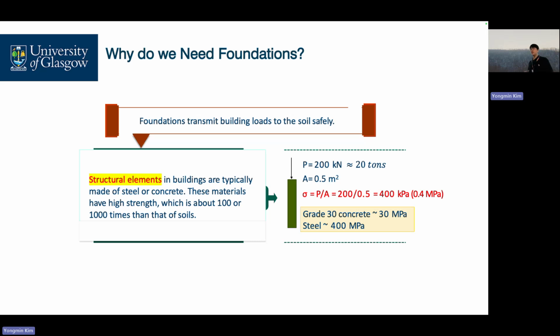Just to remind you of your civil engineering modules, concrete. What is your typical concrete grade? 30 and 40 megapascal. 30 megapascal means 30,000 kilopascal. That's way bigger than our soils and the pressures acting on our piles. It means the concrete itself is strong enough, very strong.